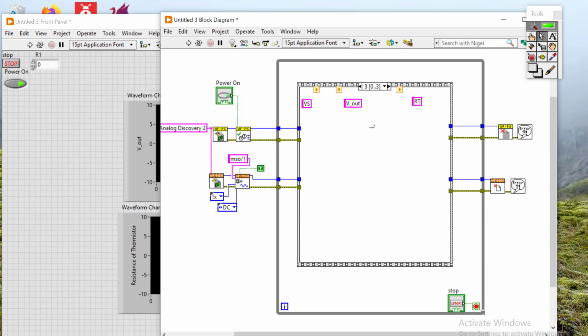to calculate the temperature, you're given in the slides a table of values for different kinds of thermistors. And the thermistor we're using is a 10K thermistor. So if you go to the column that says 10K, you'll see a whole bunch of resistance values. But on the left-hand side, there's a whole bunch of temperatures.